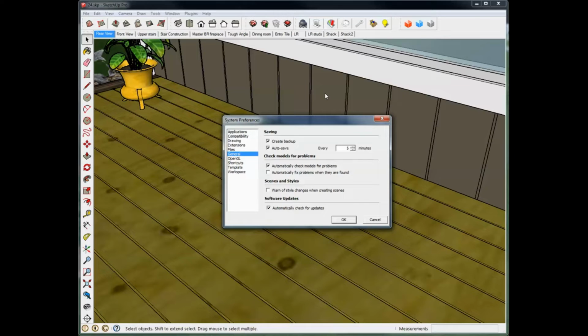So the nice thing is, you can say, okay, well, I'll go back a few drawings, and you can grab whatever it was you deleted and just do a simple copy, go back to your new drawing, paste it back in, make sure it's in the right location, and be done with it. Just a great idea. Continue to save your drawings with different names as you go. You can go back and grab sections of previous ones if you screwed it up and bring them together.